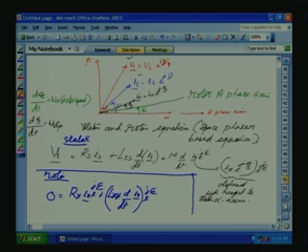So, here this e raised to j epsilon is for the voltage term we are transferring to the stator. So, this will not come into the d by dt. So, LRR into d by dt IR underscore is the voltage appearing in the rotor circuit due to the rotor self frequency. Now, this voltage term we are transferring to the stator by e raised to j epsilon.